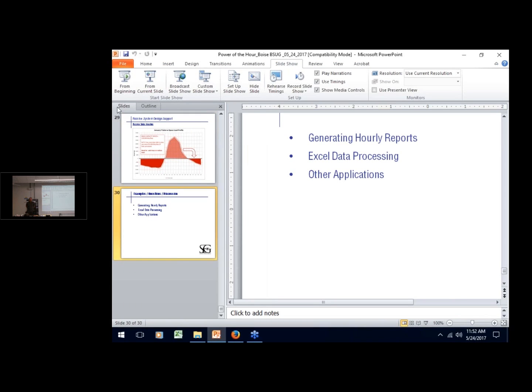Yeah. Okay. Can eQuest just run on a design day, so that you don't need to do an analysis on all 8,760 hours when you're just focusing on peak loads? The answer is no. In eQuest and probably most hourly simulation models, you have to define a simulation period.